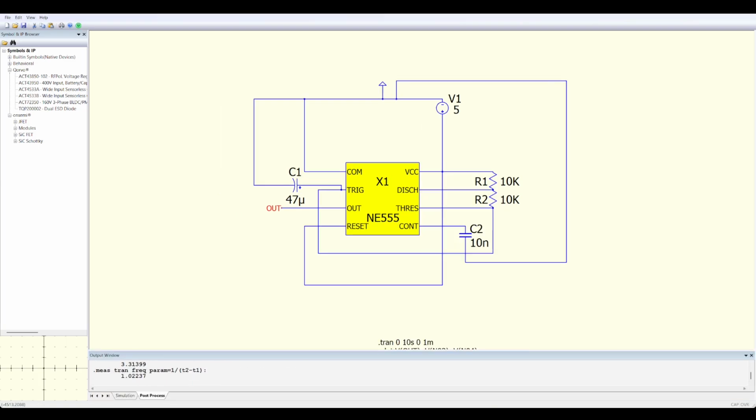All right, so you see that fat pulse in the beginning there, so ignore it. But yeah, you've got your output pulse to 5 volts. I'm not dealing with that whole LED business. And then you've got, I guess, red or green is the capacitor. It goes to 1/3, it turns on, it gets to 2/3, it turns off, it drops out, it charges again, 1/3, 2/3, and so on.